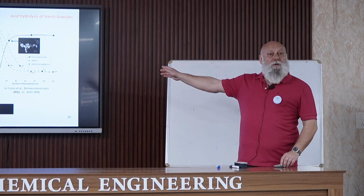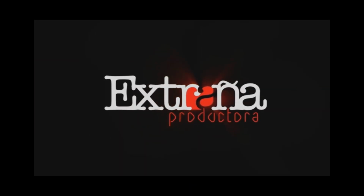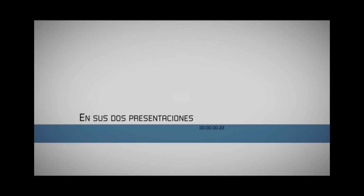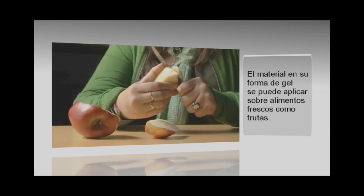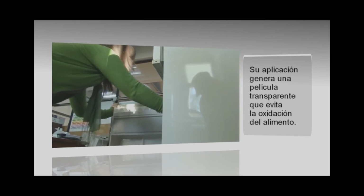In fact, starch nanocrystals have been used to reinforce thermoplastic starch. So it's a starch composite. So it's a very good composite. And this gel can be used to coat fruits, for example. And it provides some mechanical properties, but also barrier properties, because the diffusion of gas is very difficult because of these dispersed nanocrystals. And so it extends the lifetime of the food. And also, you can eat this coating or this packaging because it is starch.